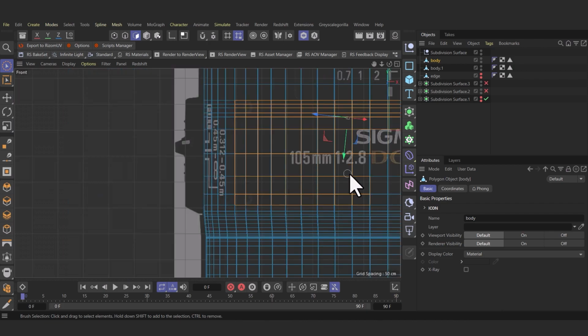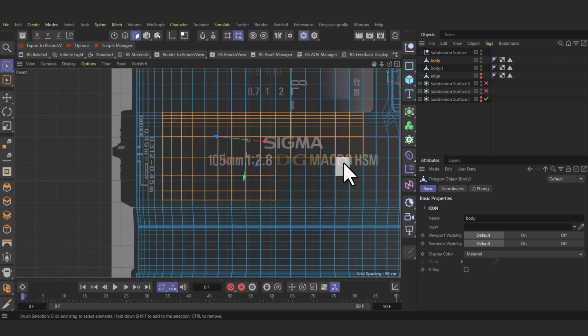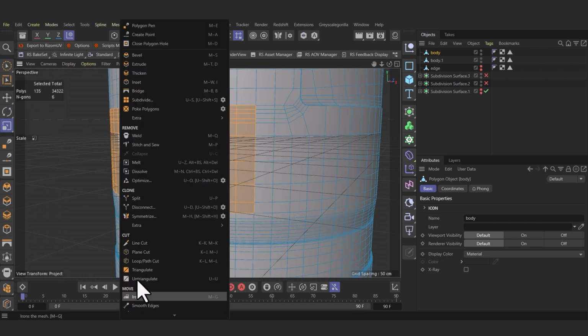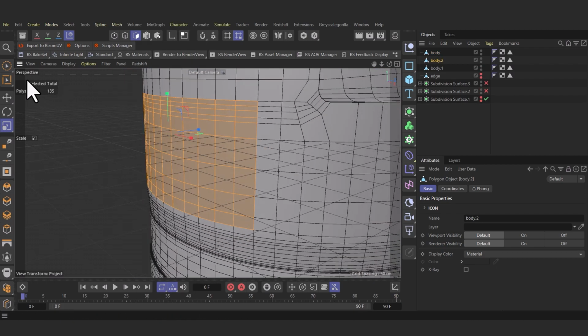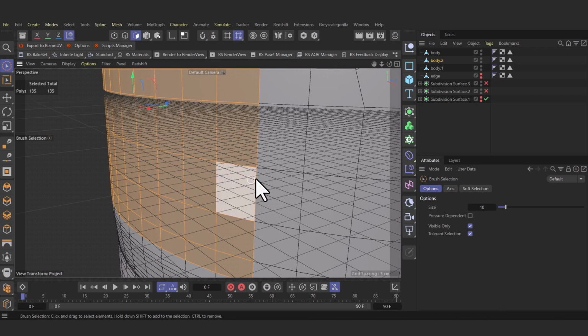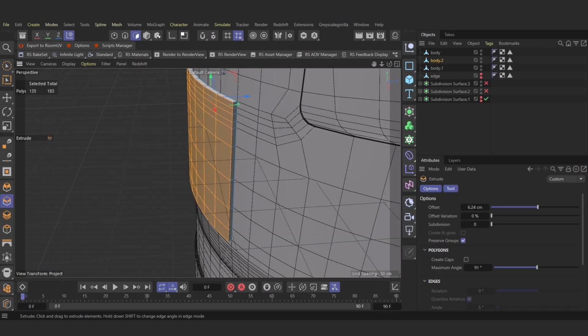The buttons, just like last time, I want to work exclusively on that piece and not have anything to do with the rest of my model. Well, I can make a copy of my model and I can select the area I want and right click on the split option. Just note, the split takes an exact copy of the desired location and delivers it as a separate layer, but the same area is still present in the main layer. So if you want, you have to delete that part manually. Okay. I'll extrude this part and stop and extrude again to make two pieces.